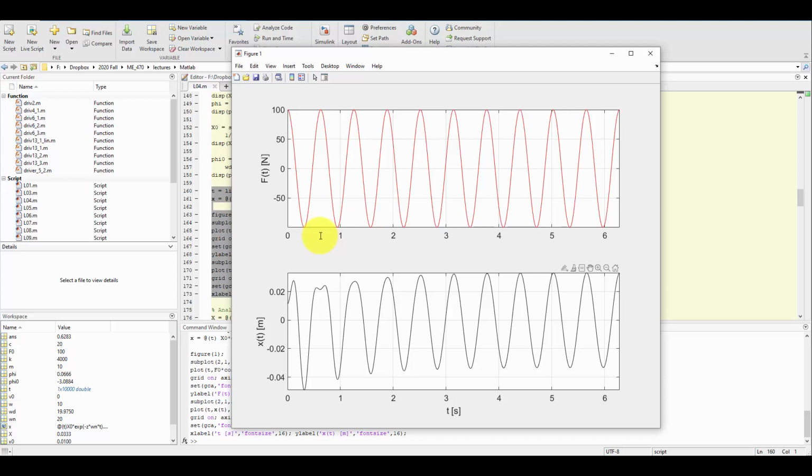We still have that second oscillation happening at the natural frequency, but it has that exponential decay going on. As time goes on, the exponential is getting smaller and smaller, so the homogeneous part is having less and less of a contribution. What we have left by the time we get to the 8th, 9th, 10th cycle about here is our steady state response. Our oscillations in our system are at the same frequency as our driving frequency, the 10 radians per second.